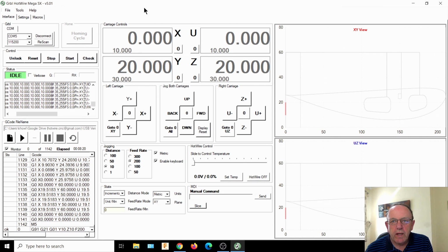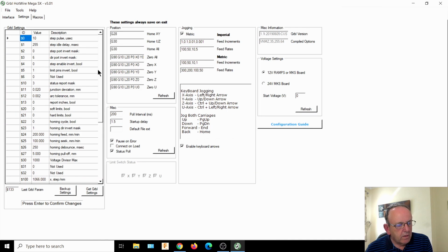You should be able to install it without any issues alongside the original software, version 4. And I'd probably advise you to keep it like that until you're happy with it and before you make any changes. And you can just make sure you've got all the same settings. The settings on the GRBL controller, the settings on the Arduino controller are stored in the EEPROM, so it will pull all them settings.